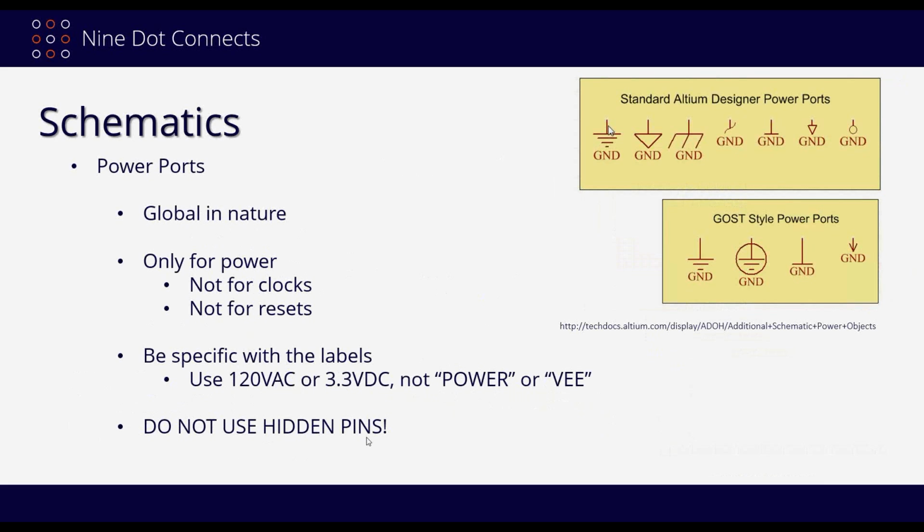The other thing that I will highly caution you on is the concept of hidden pins. Hidden pins are extremely dangerous. I do not like them. I wish they would get rid of them. I know that some of the older libraries in Altium used to use them. The reason I don't like them is because when you hide hidden pins, you've got to give it some type of name. And what happens more often than not, especially with the power pins, is that you're going to guess at something and it's not going to be right because there's so many different ways to describe your power.